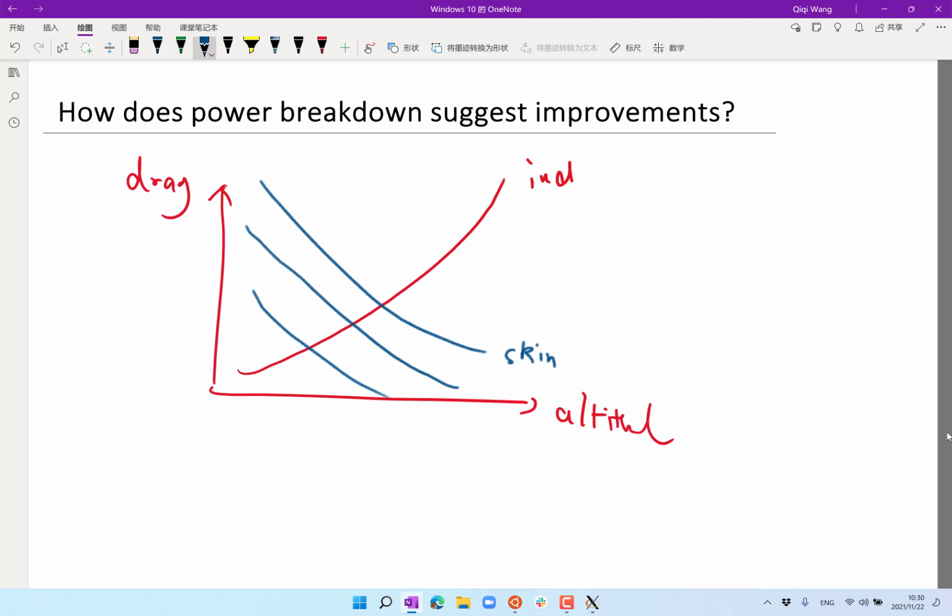Actually, that's quite similar to the answer I'm going to give, that especially at lower speed, having a small chord length may require you to have an unfeasibly high lift coefficient. This is when we are getting close to starting to design airfoils, right? How much lift coefficient you can achieve really depends on what airfoils you have. So it is always reasonable trying to keep the same span and just having a smaller and smaller chord length, having a high aspect ratio wing.